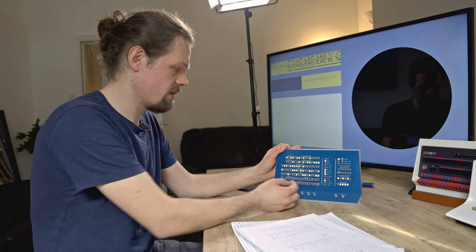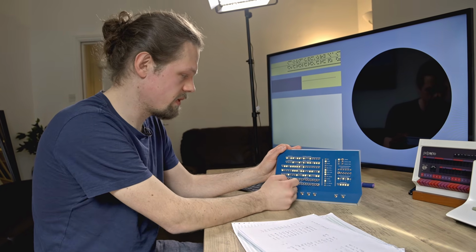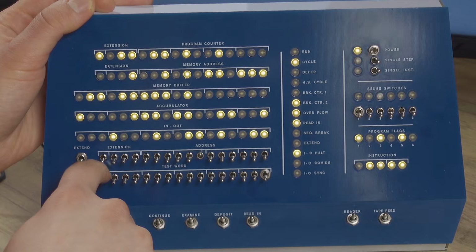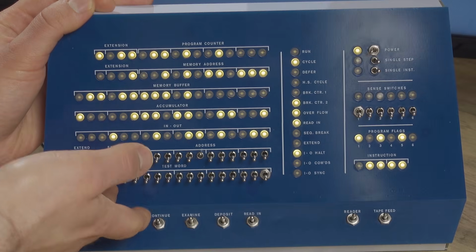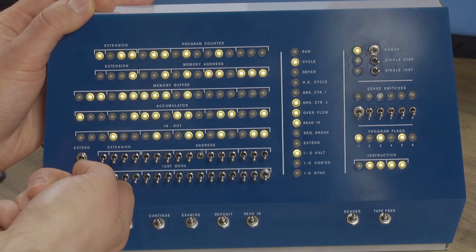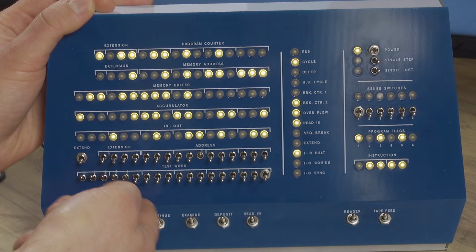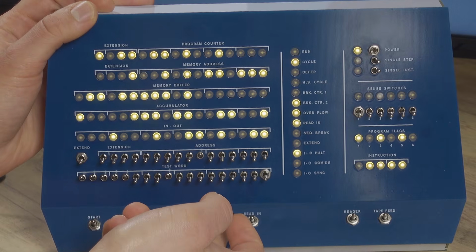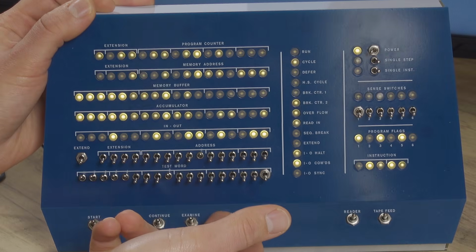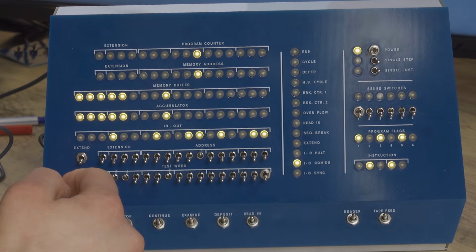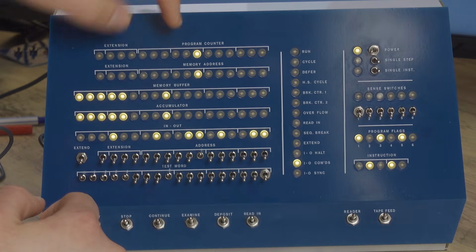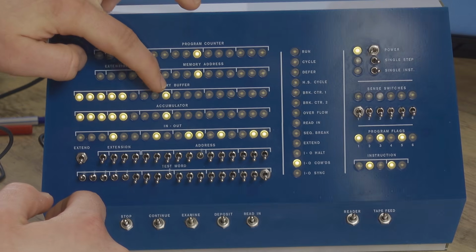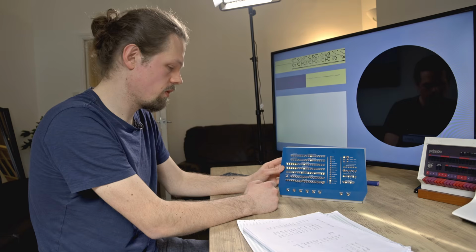So let's do a couple of instructions manually with the front panel. We start at address 100. And the word that's supposed to go here is 7, all up, 6, which is 4 and 2, 1, and the rest zeros. Now pressing deposit puts this into memory. We see memory address 100 and memory buffer 761000. Oh, actually I made a mistake.